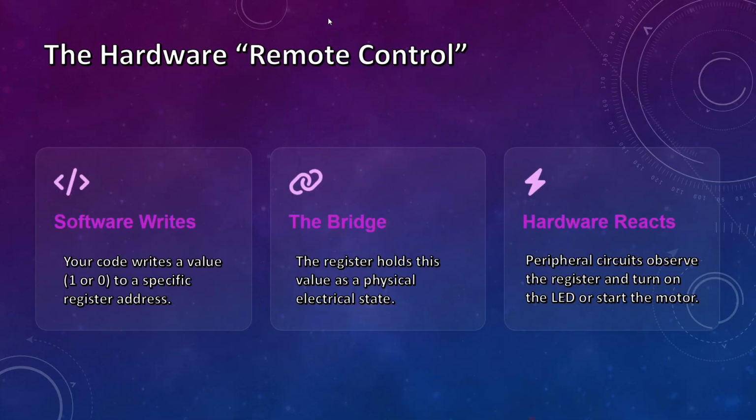Now, let's move beyond the CPU. Suppose you have an LED connected to a microcontroller. Can the CPU directly touch the LED? No. Can the CPU physically switch on the LED? No. There needs to be some mechanism between software and hardware, right? And that mechanism is registers.